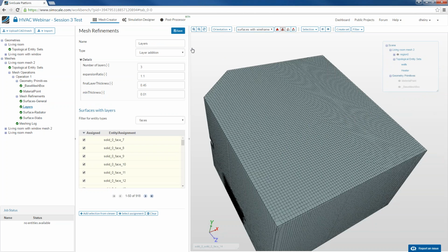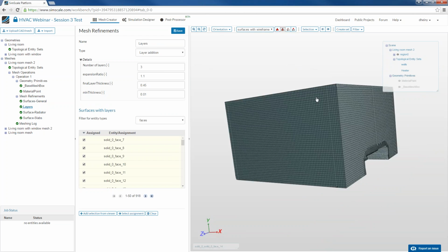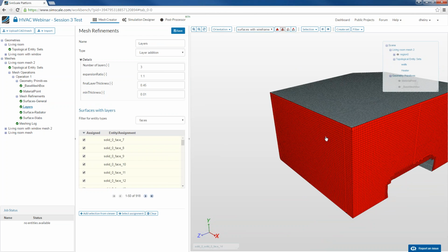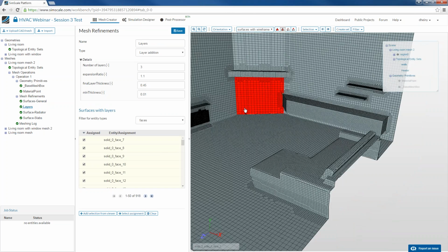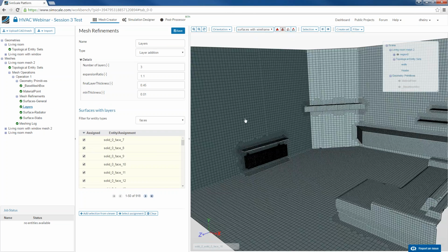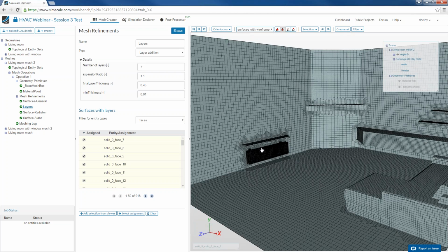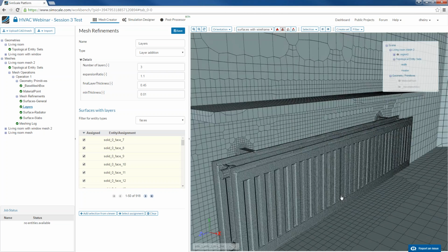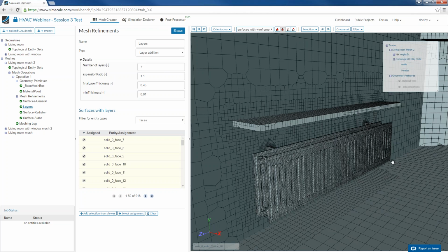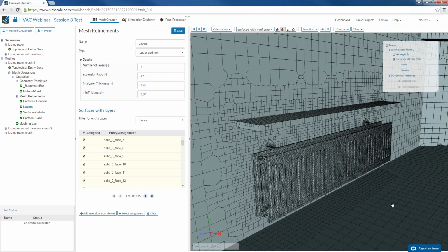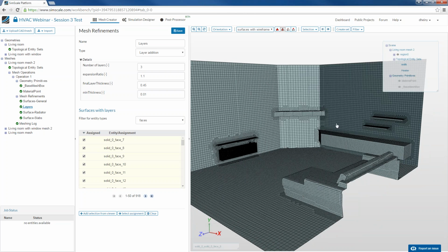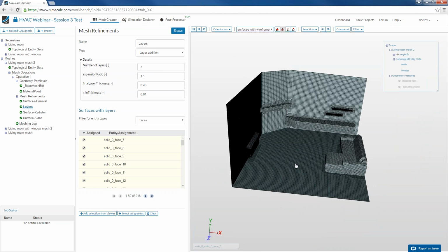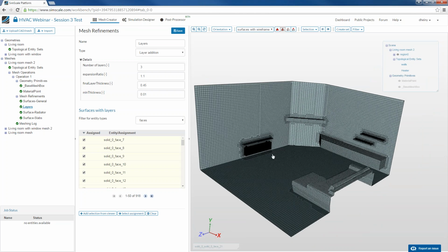And here you can see now that we have a finite volume mesh being generated. So we can look into it, we could now slice it, etc. But we're running a bit out of time, so I need to speed up a bit. And here you can see all the refinements that I applied. Close to the radiator, I have the detail of the radiator with the level 4 refinement assigned. Can you see that the slabs got a level 2 refinement, so all of this worked nicely. So this is exactly what I wanted to have.